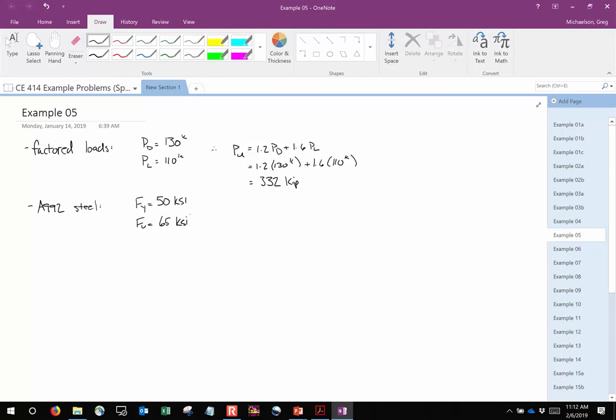Here's sort of a rule of thumb of what that means. If I go down to Huntington Steel and I purchase a W10 by 49, chances are it's going to be made out of A992 steel. If I go purchase, let's say, an angle, what do you think it's going to be made out of? A36. The point I'm making is this. If you don't know, go with the preferred material spec.